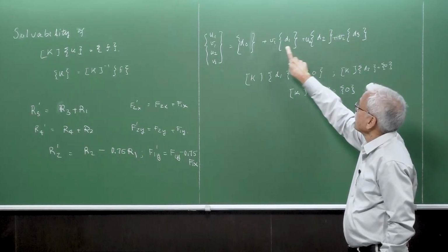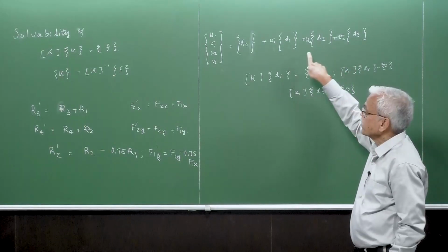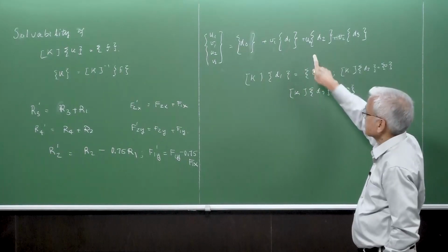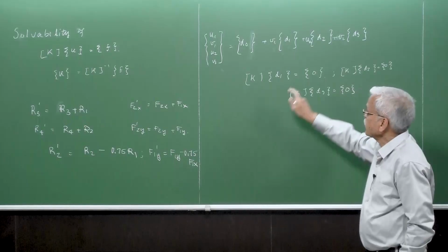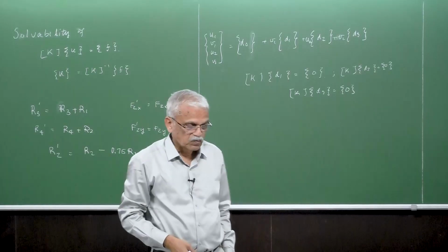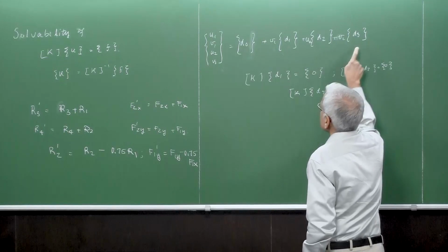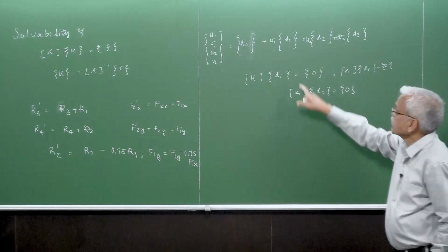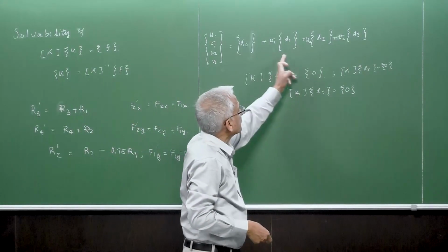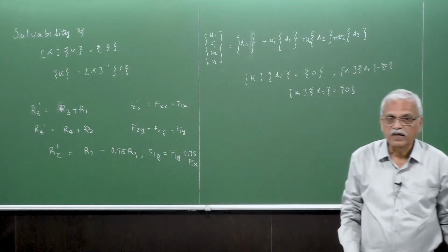So however, whatever be the value of V1, U2, V2, if you apply here, it doesn't matter, and it doesn't cause any elastic deformation, it doesn't cause any stresses. Okay, so the important thing for you: to completely solve the body for elastic deformations, you have to arbitrarily put these things. Another very important thing is that these D1, D2, D3 are rigid body deformations, or for that matter, any combination of this is also a rigid body mode.